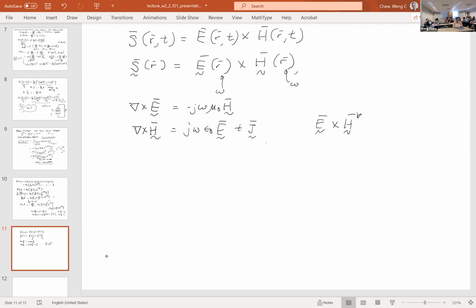complex conjugate. The reason why we put a complex conjugate there is that we have been motivated by circuit theory. In circuit theory, what is the definition for complex power? In ordinary circuit theory, we have this being instantaneous power, but if V and I are converted to phasors, you see the complex power is this.